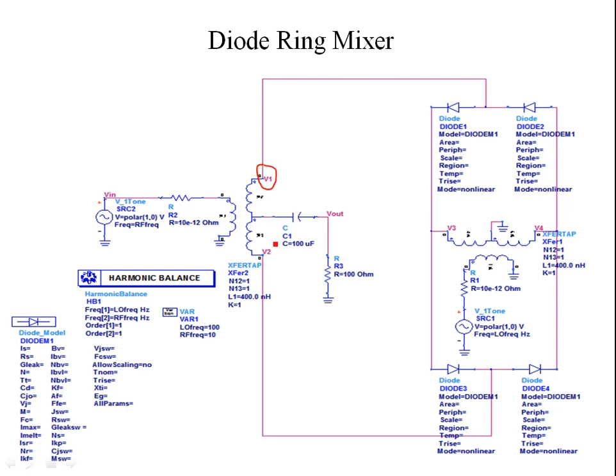Now once you connect the local oscillator part with the RF part over here at the voltages V1 and V2, what happens is that you start mixing up the currents. So you mix the local oscillator current over here with the RF current, right? So what happens is that at the return path you will have a modulated output.